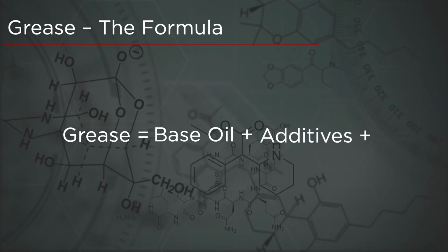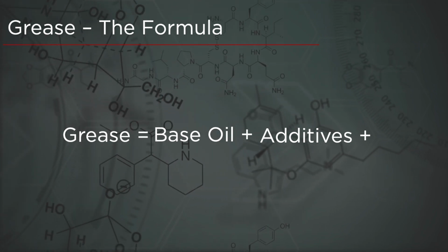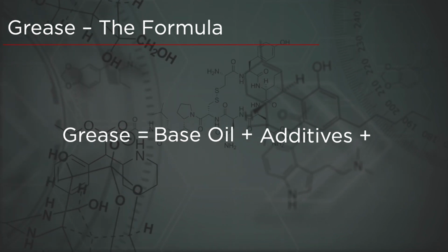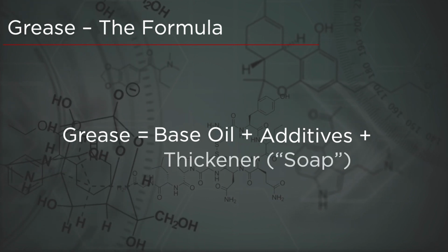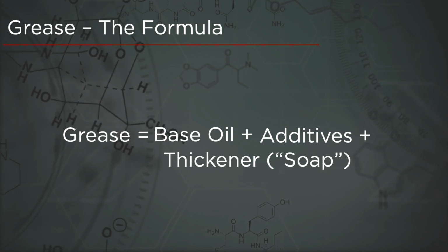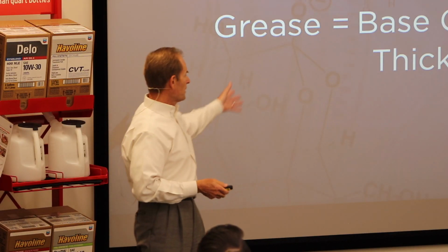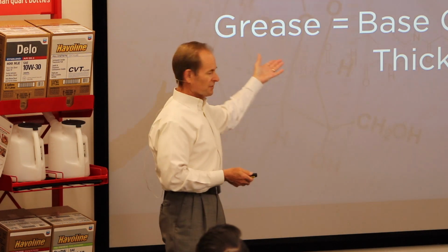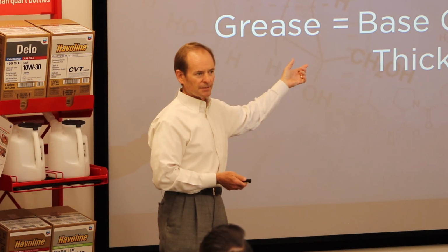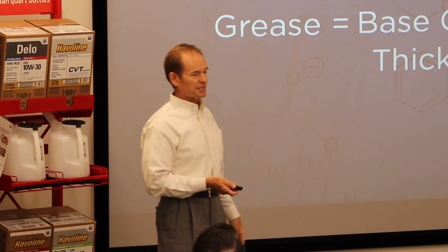and you have some additives to improve the properties of the base oil or the performance of the grease. What's different about this formula is we also have a thickener, okay? Something that's going to give it its gel-like structure. All right, but otherwise, most greases are kind of like gear lubes. They have the same kind of base oils, the same kind of additives, but with this thickener.